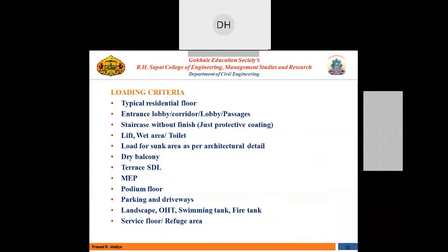This type of area will be there once you go for a high rise building. When I say high rise, it is a building which is above 50 meters and up to 250 meters in height, right? For buildings above 50 meters height, you have to keep one floor after every 10 floors as a refuge floor, where in case of fire emergency, the people can gather, and that floor is called a refuge.